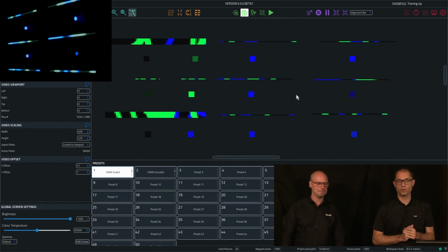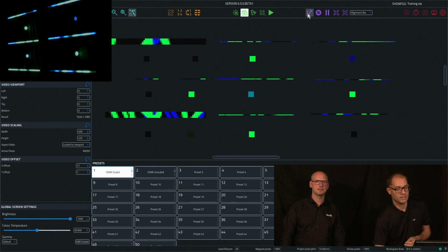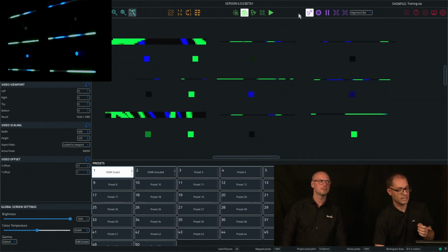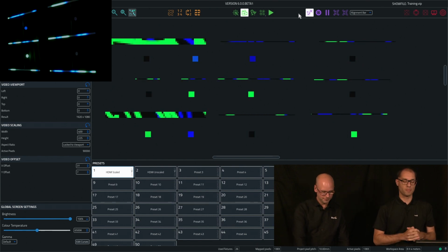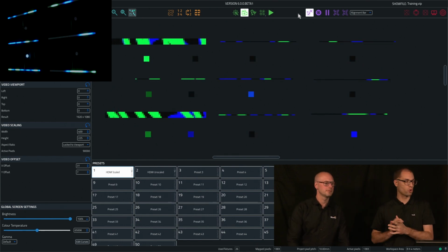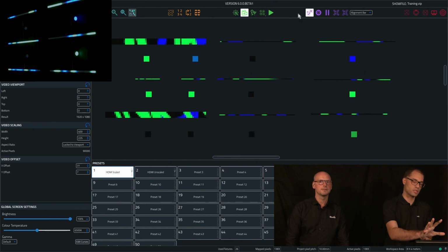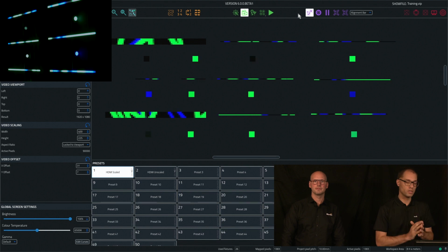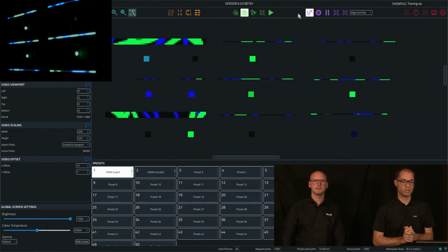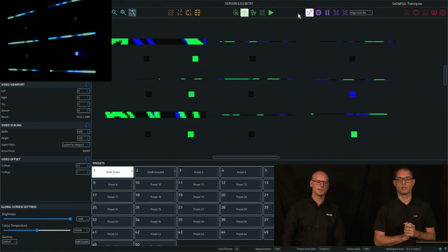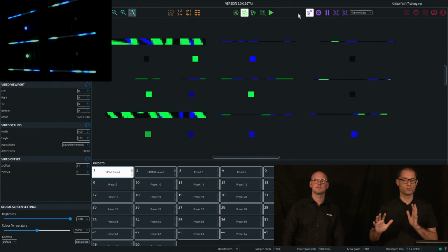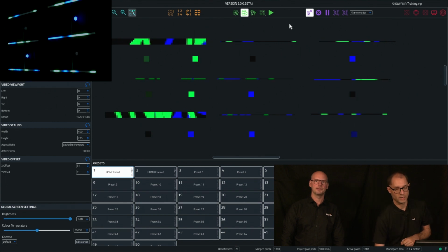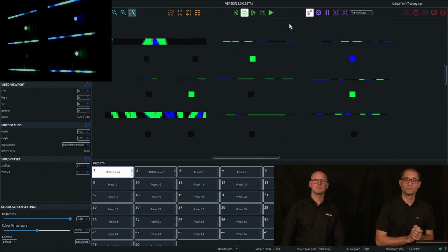The last thing you might want to know about this is that we also have a disable controls button here on the toolbar. This basically disables any DMX input to the P3 controller. So if something goes wrong with what you're getting from the lighting desk, if you disable the controls with that button, the fixture will just revert to purely showing video, completely ignoring whatever's happening on the lighting desk. So that's a really nice lifesaver if they're rebooting the console or still working on it. You can just have them running in pure video mode as well. So there you go.